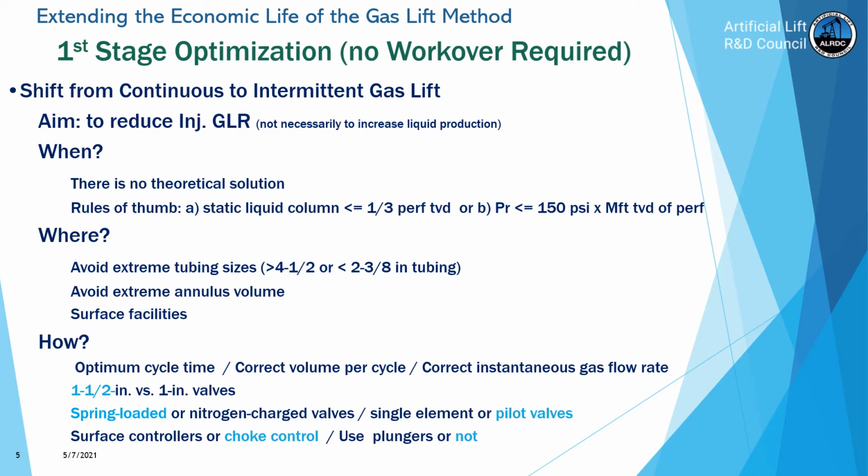But at the same time, if we have a large number of wells, then with choke control we don't need to install intermitters, so you don't have to spend money buying those controllers, and then you don't have to maintain them, because they need maintenance.